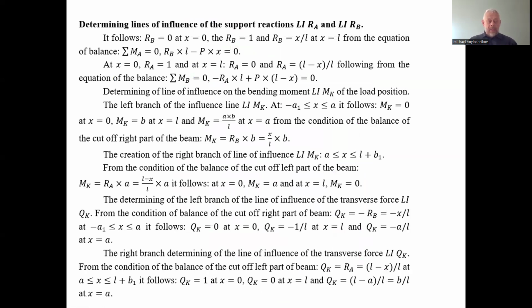So we have another balance equation. We remind that P equals 1, so from this linear balance equation R_A equals (L minus X) divided by L, where L is the span between the supports. Next we can find that if X equals L, the unit force is at the second support, and R_A has to be equal to 0.